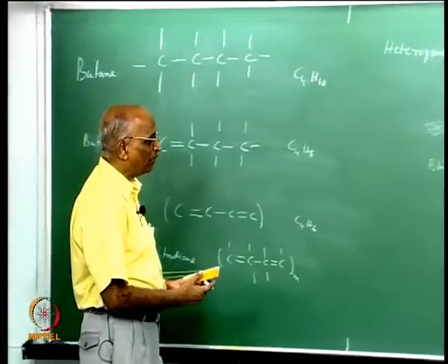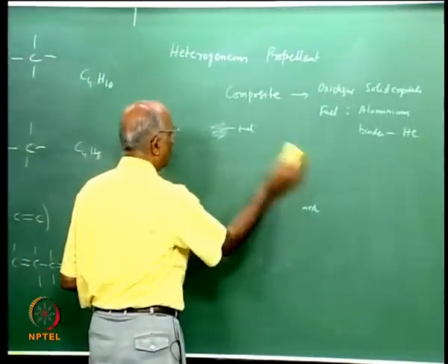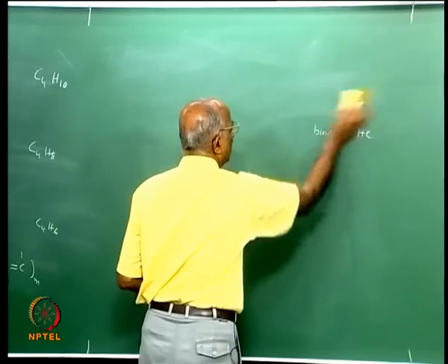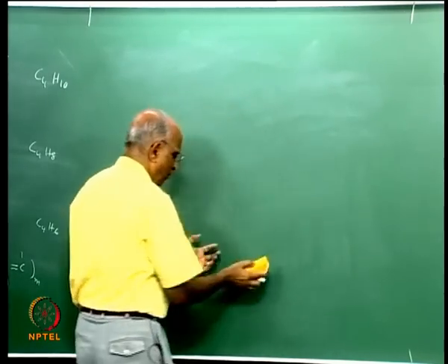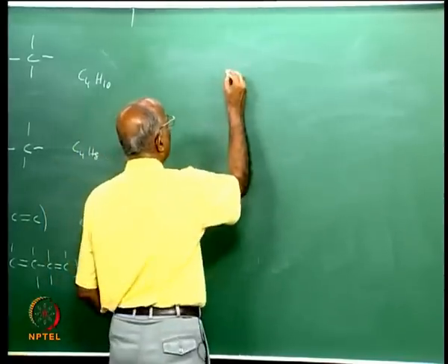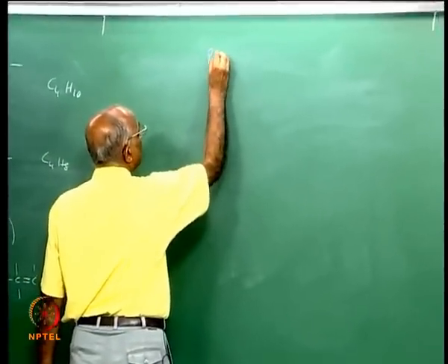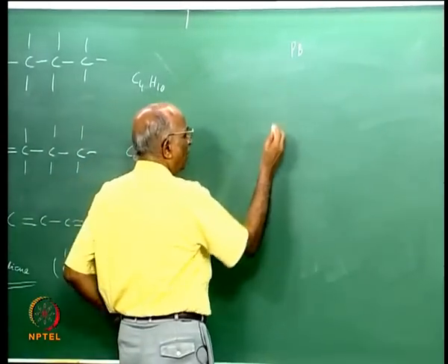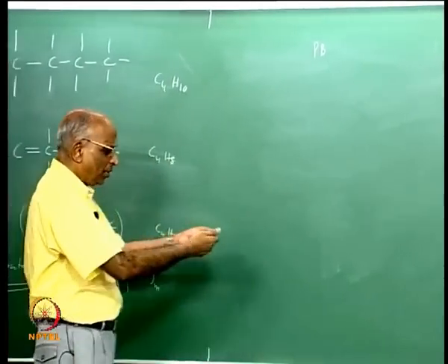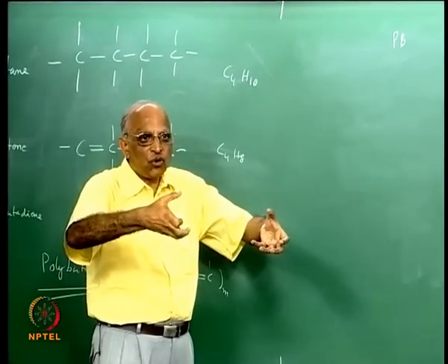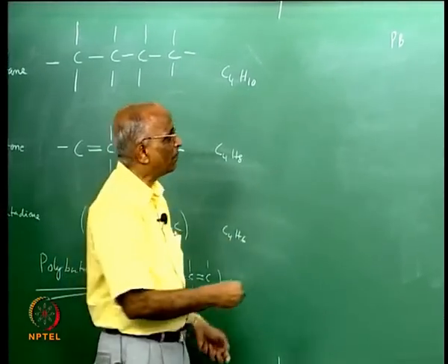I come to the actual fuels which we can use, or the binding agent. I want to make it into a good polymer, something which has a long chain which can keep the oxidizer particles in it. Therefore, I take this polybutadiene whose structure I have just given. Maybe this is something which is a chain, a chain is something which is elastic, it will keep on pulling. I need to make it a little strong such that it can hold things together.